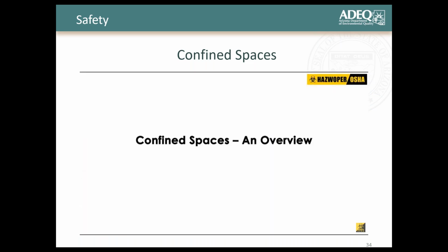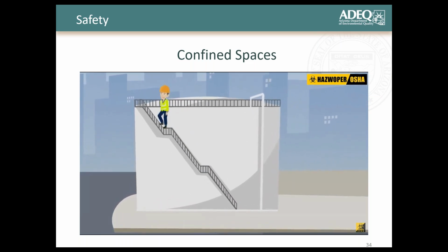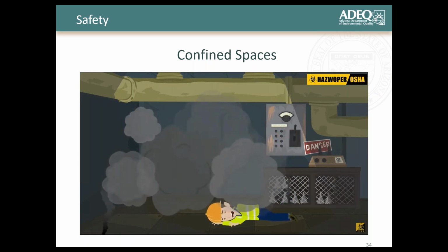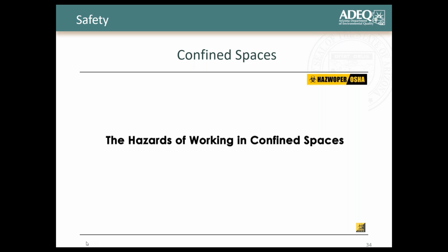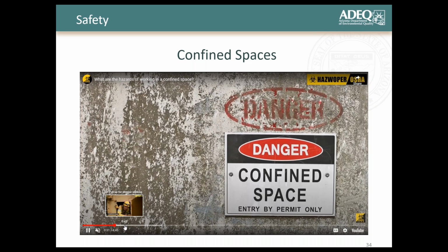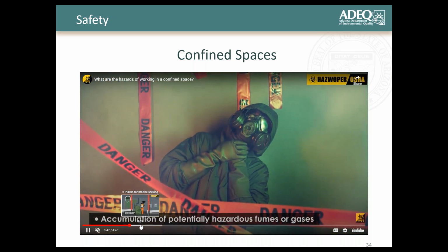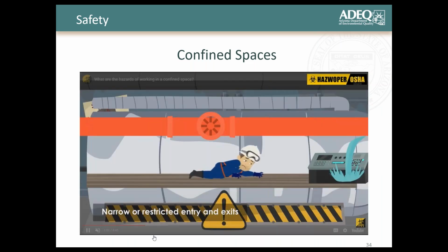But the most important thing to realize in a confined space is that if an emergency happens, you can't be an additional victim. And I think before I started the video, it showed the stat that most of your victims end up being would-be rescuers. So it's important to keep that in mind. I'm going to skip through some of these. Confined spaces, like we talked about, are very dangerous because of the accumulation of gases or potential hazards in there.